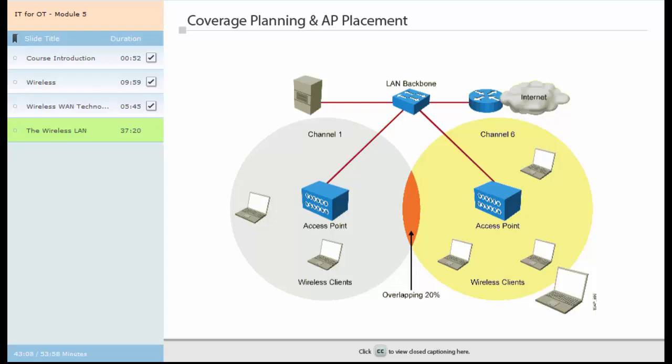You must consider many factors when calculating coverage and capacity. Transmit power and receiver sensitivity. The transmit power is the strength of the signal output by the transmitting radio, and the receiver sensitivity is the ability of the receiver to detect the signal. These factors are the cornerstone determinants for coverage and range. Antennas on both the transmitter and the receiver boost the signal strength, allowing a larger area of coverage. The antenna pattern is also a critical element of the system design.